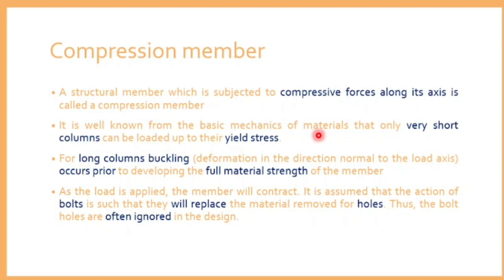The beam is there, below that you have the column, and it carries the compression load practically. The way you test is different from what actually exists. You are finding the yield strength. That is why the second point mentions a very short column. You have three types of column: long column, short column and intermediate column. According to the cross section and the height, it is called the slenderness ratio. With a slenderness ratio limit, you can classify columns into three types.